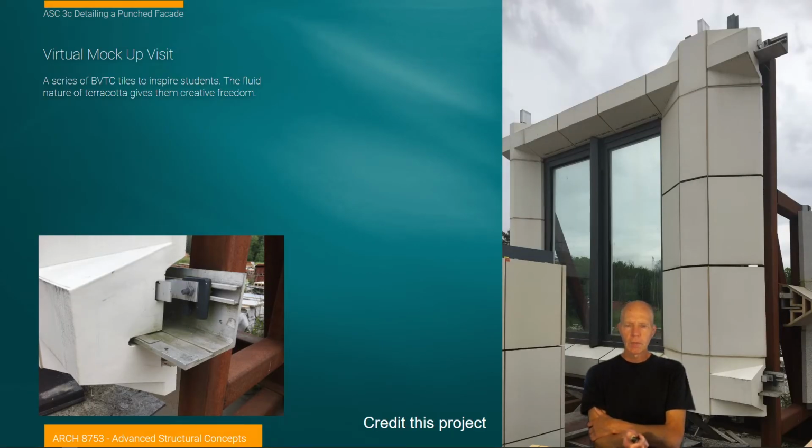So here we have a typical mock-up. I don't have the credit for this project, that's the little sign below it. But you see a close-up detail of the massive elements that are there, the really large expansive clip systems. Actually, you can see a little thermal break between the exterior clip and the channel that it's attaching with, that little piece of black washer that goes between it.